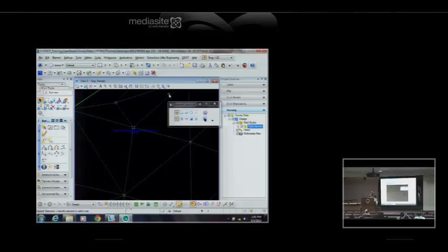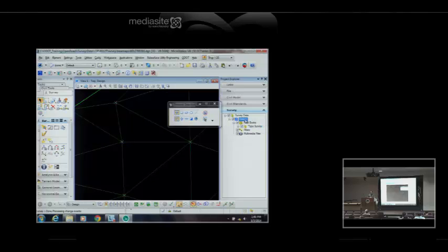I mentioned undo, so I just undo those two, and I'm back to where I was. So part of the DGN integration is to enable those types of things that otherwise you couldn't do. I mentioned survey processing rules, and that happens, I believe, on the model. Yeah, there's a deactivate survey processing rules. So if I turn that on and move that X, it will move without updating the terrain.